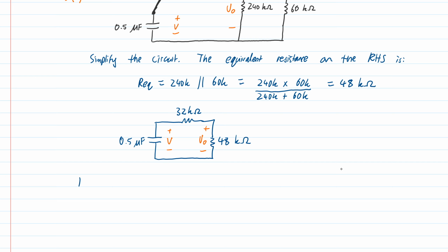So analyzing this circuit, we need a circuit equation that describes its dynamics. Here we have a loop, so I'm going to use Kirchhoff's voltage law around this loop. Let me first label a current that's flowing in this loop. An important point so that my positive and negative signs are correct: if I want to use my normal capacitor equation, I_C is C dV/dt, that is true for voltages and currents defined according to conventional current.